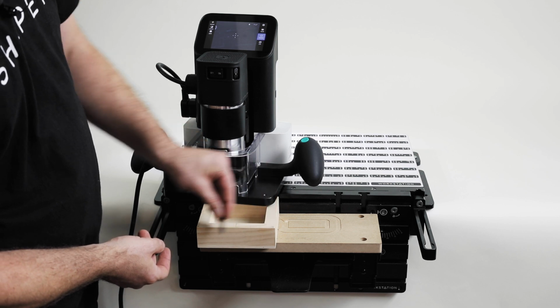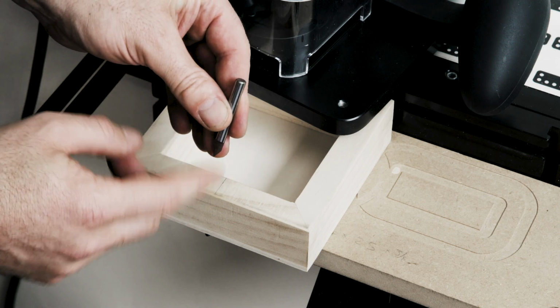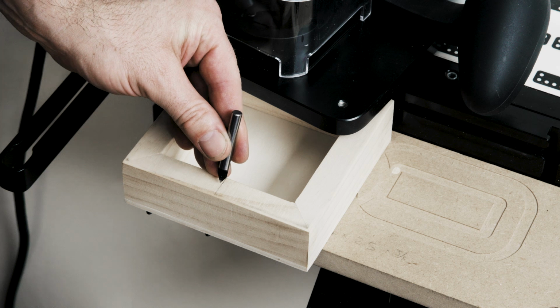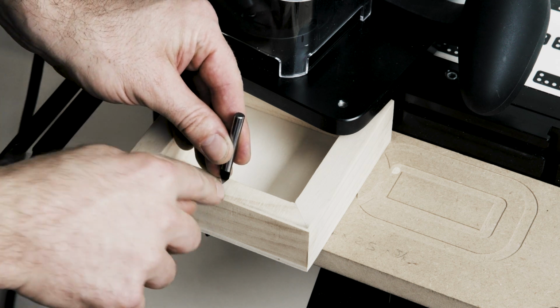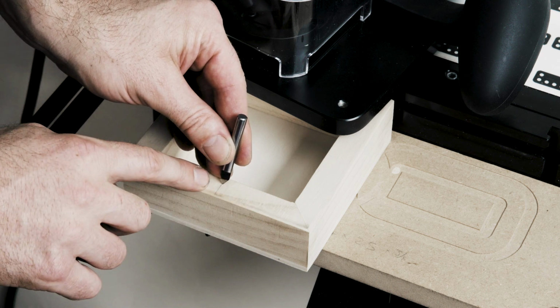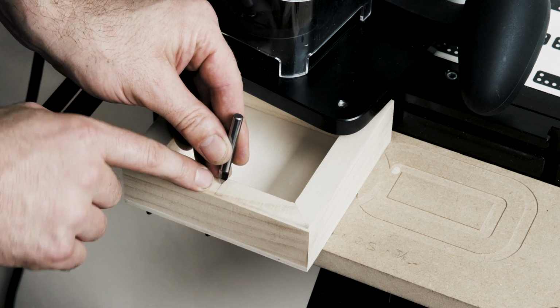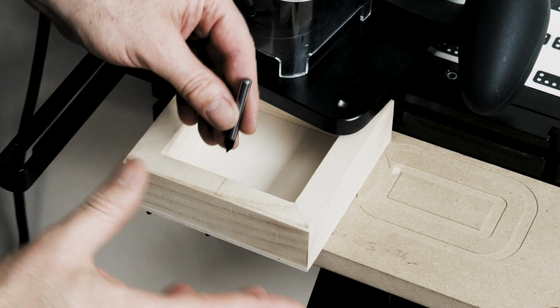There's then a hybrid approach, where you probe 2 points. You would use the cutter with a point, the engraving cutter, and then raise the cutter up and visually probe the point of the cutter itself hovering above an actual line. You would confirm you're exactly aligned with the pencil mark and then probe using that approach.